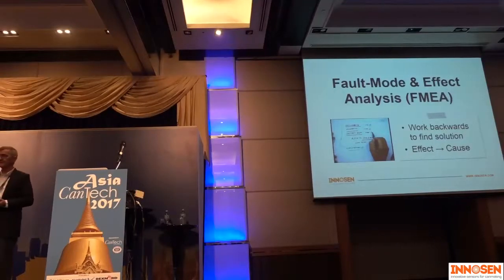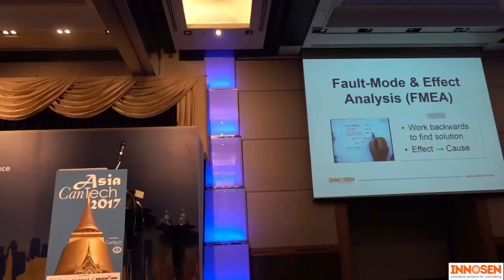Now you could, of course, start measuring, you could make corrections on the process, you could perhaps have different spreading magnets, you could have higher blast air on the sheets, you might have different sized sucker cups, you might control your vacuum better, you can do all those things, but you still, every now and then, are going to get a dull sheet.